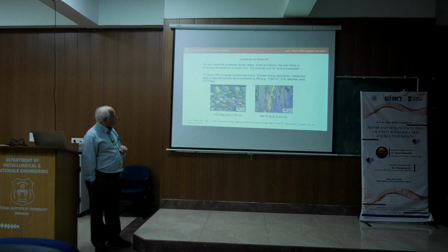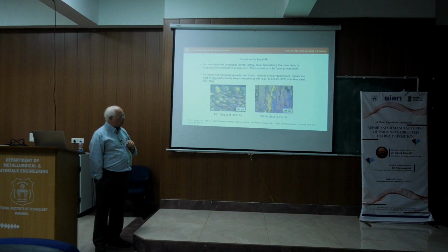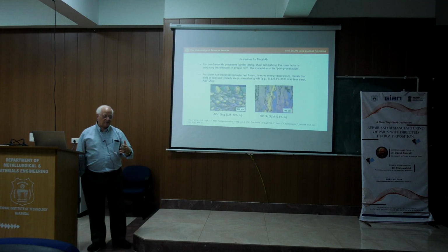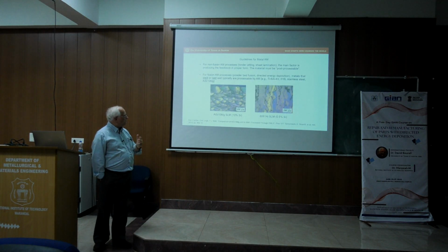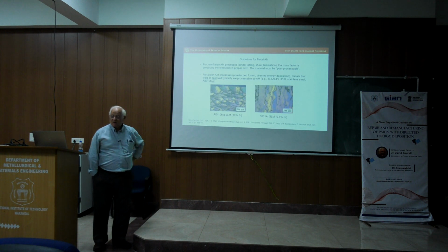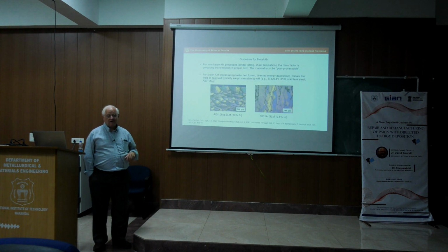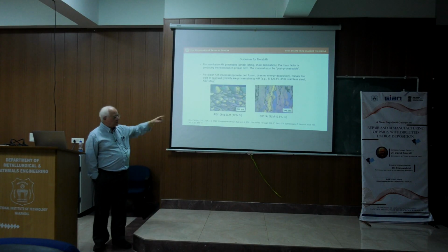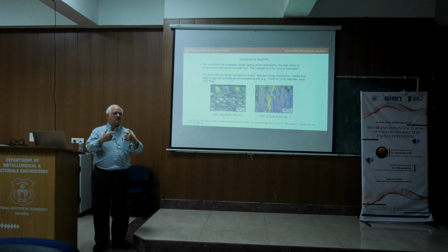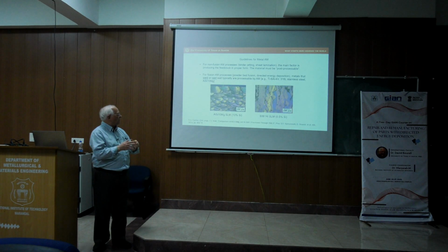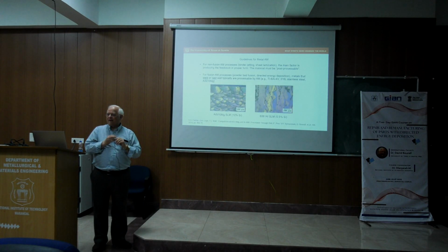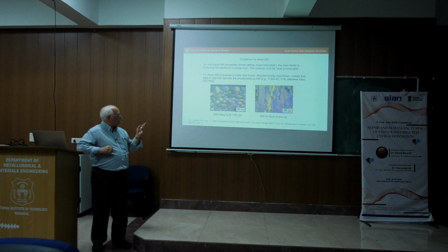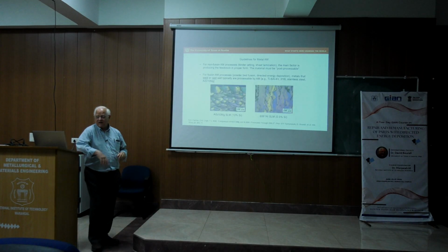The dark features on this micrograph are not porosity. Those are actually cracks that have formed. The material will crack, and then with each succeeding layer, the crack just continues to go vertically upward and extend through the build. So the part's just all cracked up.